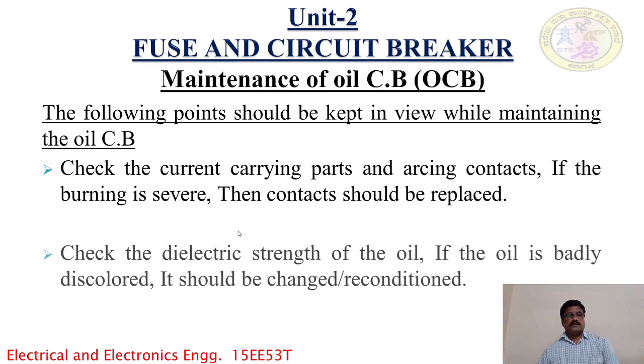The second one: check the dielectric strength of the oil. If the oil is badly discolored, it should be changed or reconditioned. Definitely, after the interruption of the fault current by the circuit breaker, the oil loses its dielectric strength due to carbonization.